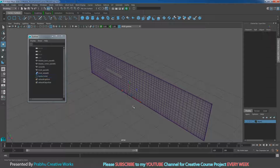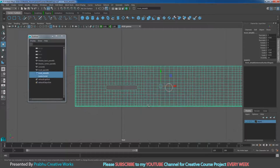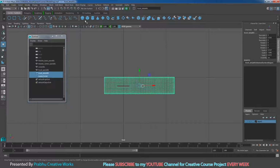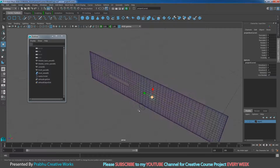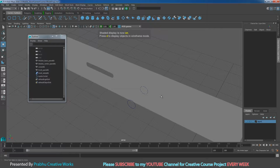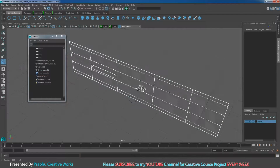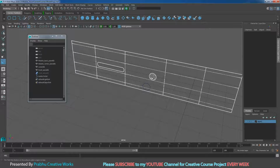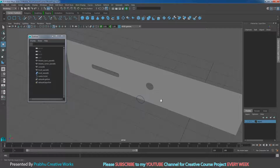So now with node circle 1 selected, shift select your front detail, go to front view. You want to do the same thing, go to surfaces and choose project curves on surface. So now the node circle will project on your mesh. Press 5 on the keyboard, you will be able to see. So with the front detail selected, go to surfaces and choose trim tool. So click anywhere on the outside, don't select the whole part. So I will select outside and press enter. So that means it will make a virtual hole on your object.